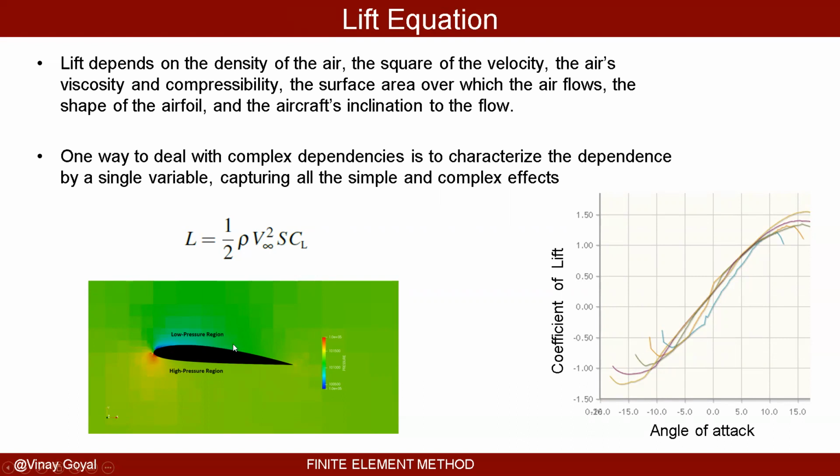You can see the pressure changes over the airfoil. We're going to make an assumption later when we do a structure analysis, assuming that the whole bottom surface has that pressure applied. And it's just an assumption. Typically, what you like to do is apply a non-uniform pressure across. And that'll be the preferred method.